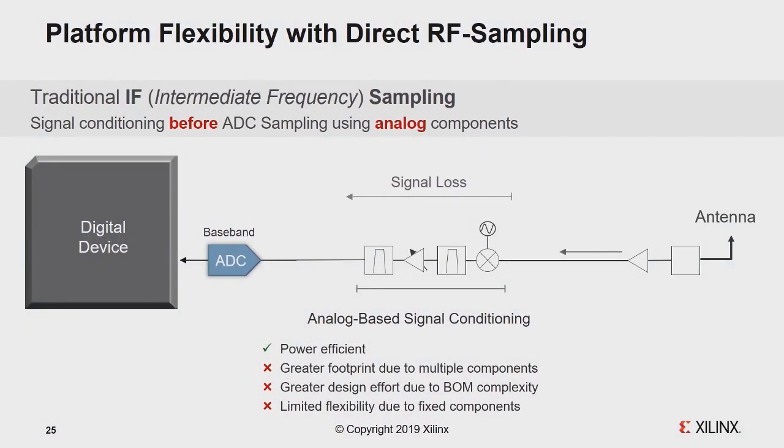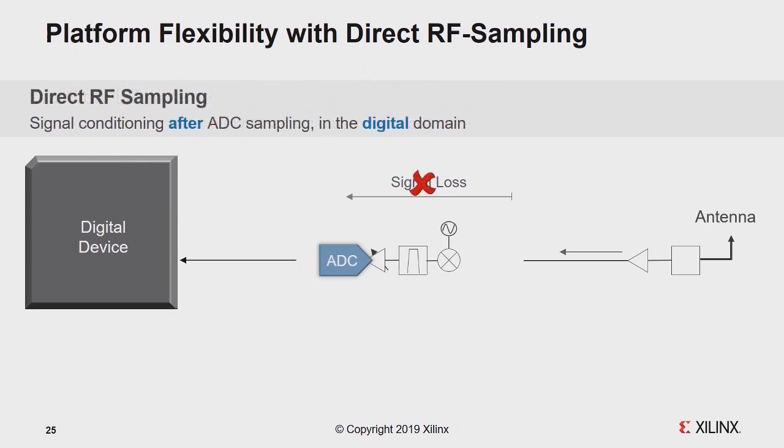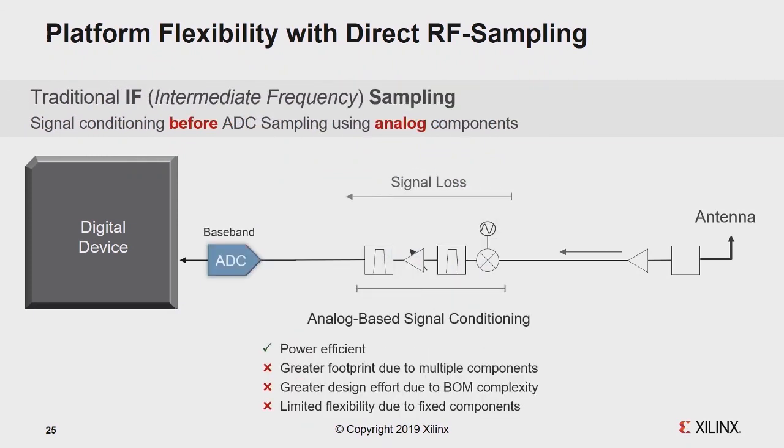First of all, we would like to review the RF system architecture. The signal comes in to the antenna, goes through the LNA, down converting, and then a bandpass filter, and then down converts to a few megahertz for the ADC. Then the JESD204B interface is used to connect the data converter and FPGA. The power efficiency is good, but it's only for a specific frequency and bandwidth. So you can optimize your passive components to optimize your performance.